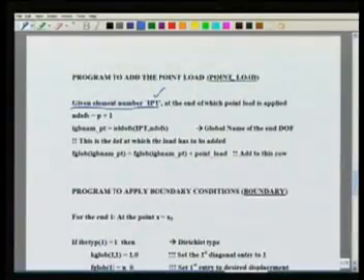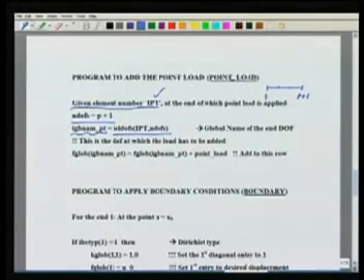Now I know that for this element there are p plus 1 degrees of freedom. So I go to the last degree of freedom, because if you remember, in the element this one is the p plus 1 degree of freedom, this is the first one, and you have the others in between. I take the p plus 1 degree of freedom and find its global name, again using my ILDOFs. You see how crucial this ILDOFs information becomes, and this is the kind of data structure that will also be used in the 2D and 3D programs, because their life will be a little bit more difficult. So I find the global name of this degree of freedom.